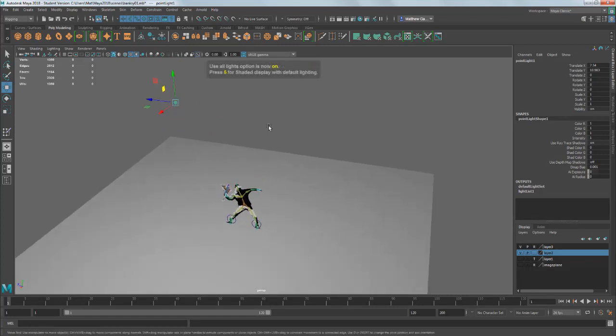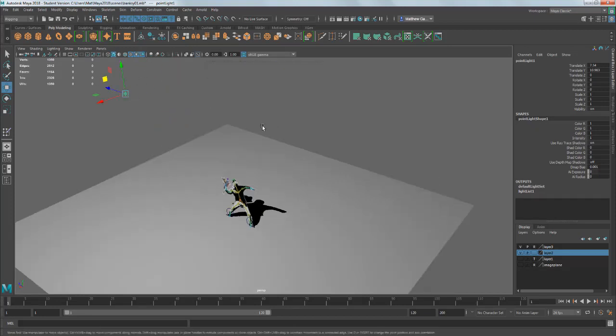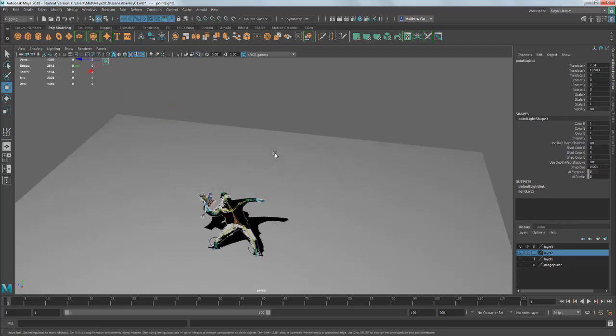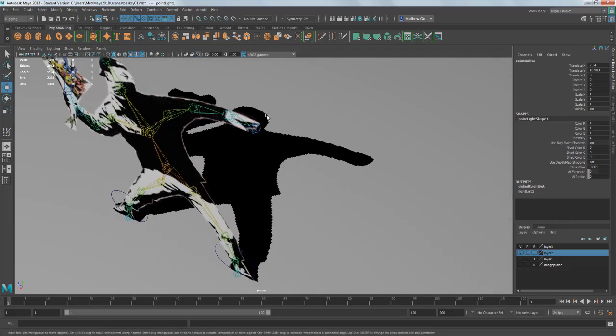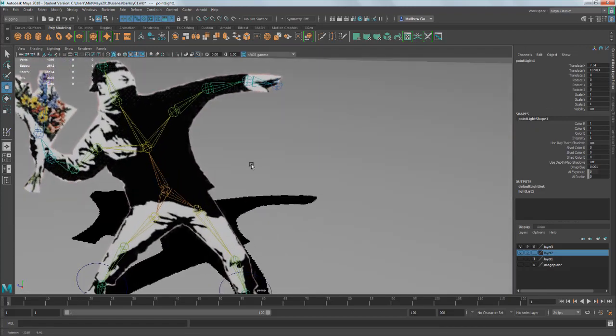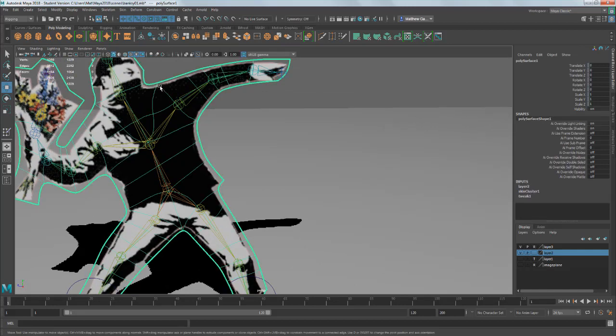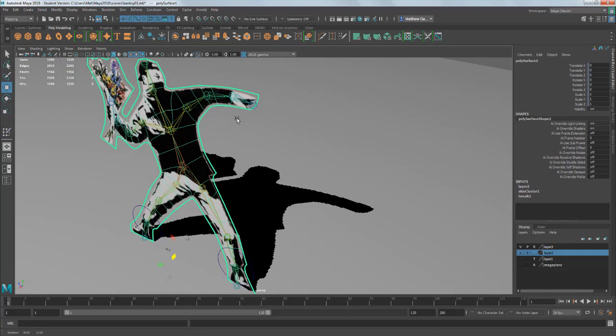And I can actually turn on shadows. So it's this little icon here. And there's the shadow for my character. Now, what's hard to tell with this is that this is not displaying the transparency shadow. It's actually displaying the edge of the polygons. I can show you this. If I press the 1 key, you can see that shadow is changing as I do the smoothing on and off. So it's not actually showing the transparency.